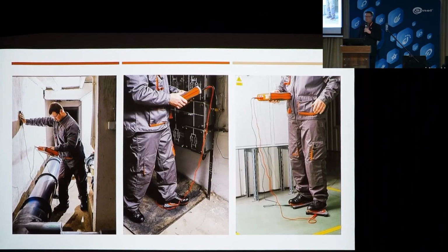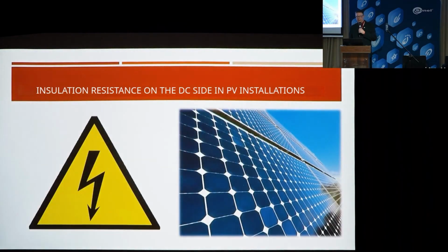It's partially conductive because we have EPA zones here, and that's needed to dissipate static charges so they don't affect anything or accidentally cause damage to sensitive components. Besides, all our production staff wear special garments designed for that purpose. Coats with conductive fibers, wrist straps, special footwear, a testing station. So measurements like that would also be possible here.